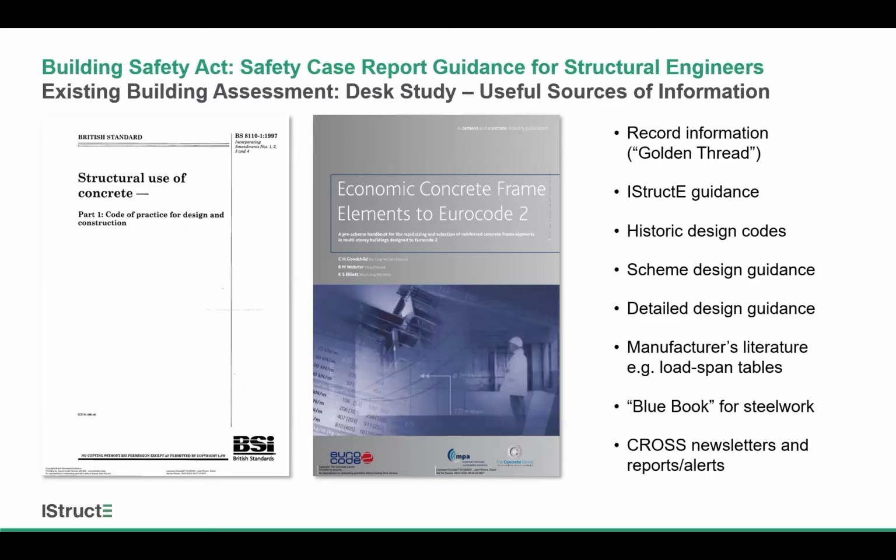Scheme design documents are also very helpful in terms of looking at initial sizing of elements to see if things look about the right size. Similarly, detailed design guidance can be useful in terms of informing what you're looking at. Manufacturer's literature, so things like load span tables for metal deck, for example, will help to give you a feel as to whether spans are appropriate as well. The Blue Book for steelwork is another example, and then the CROSS newsletters and reports are also helpful.